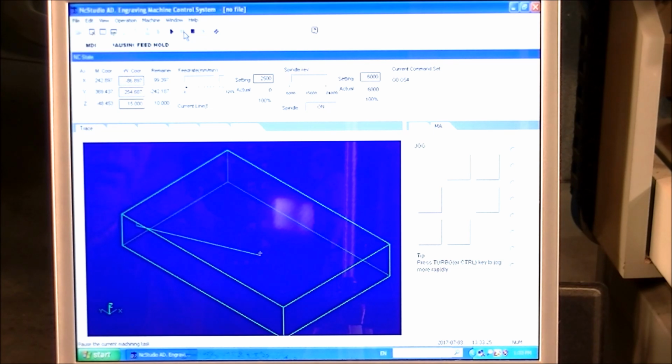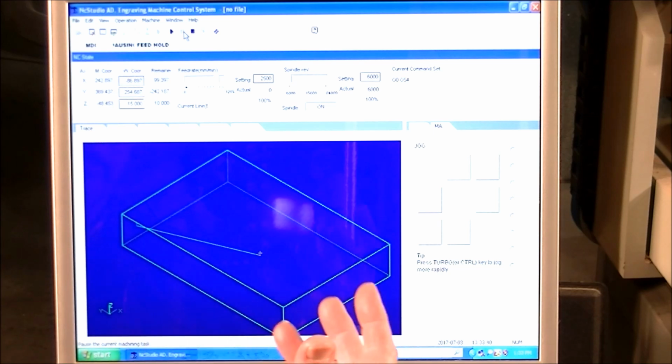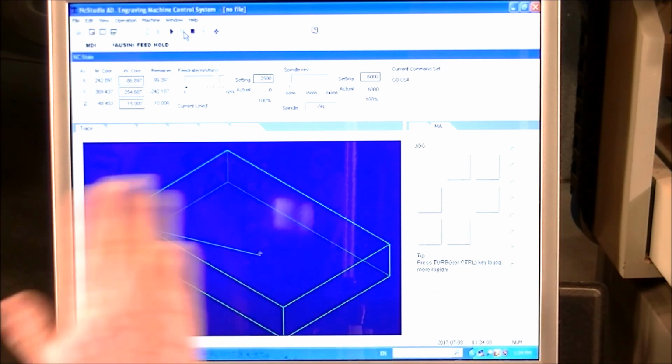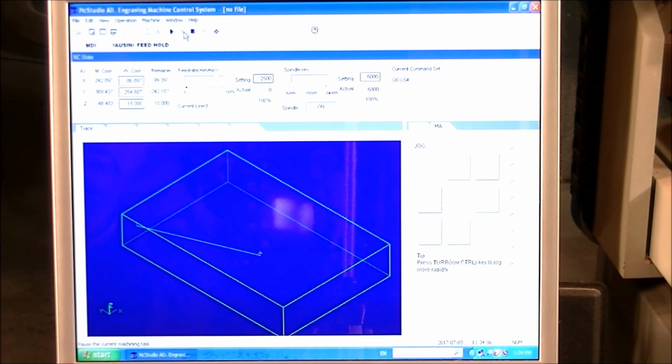As soon as you say, like, post the code, the program takes over. This is one downfall with NC Studio, but you can actually create a G code within NC Studio. But as you just saw, as soon as you post the code, the program takes over and it's off and running. So there you go. Those are the three different ways then of creating a small program for a surfacing job of a piece of material.